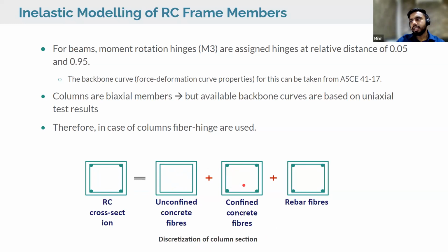So for the concrete as well and for the rebar as well, you will be giving the nonlinear property to the material, and that will induce how your structure is behaving in the nonlinear range. So that is the difference between the two.